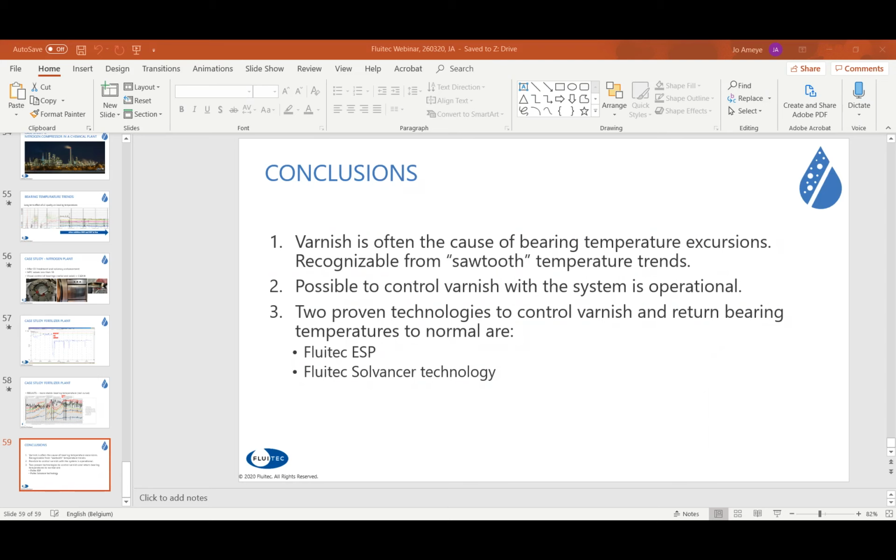Think about GTL lubricants, which are today the state-of-the-art lubricants on the market. Group 1 oil was an oil we used 20, 30 years ago, and it is still used in some countries or applications. But group 2 and group 3 oils have a better base oil, more solid and more oxidation resistant. GTLs are really 100% oxidative stable.